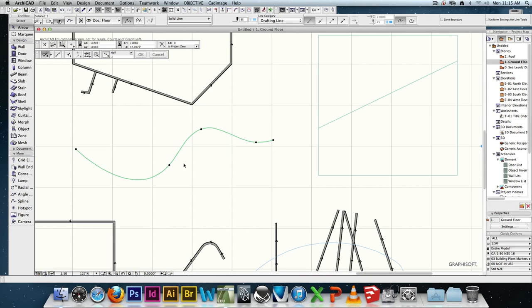but notice here I've only got so many points along here, and however I move it, it's like a flexi curve. You know what I'm saying when I say flexi curve? You get the lead-based ruler, and you can bend it. So normally you'd have several points, and you bend it to fit. In a way that's a spline. So what we're saying is that there's these points and there's these controls across it. This one here is what's typically called a natural curve, and it's just doing a natural curve to try and get through all of these points.